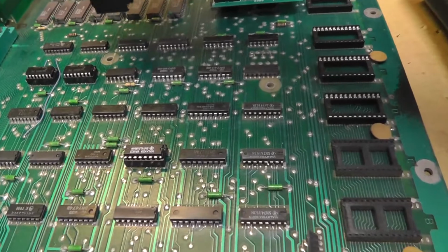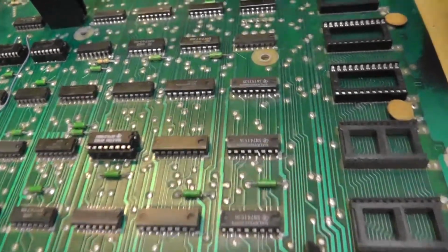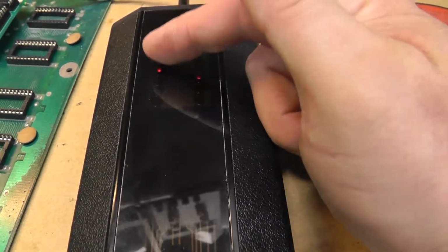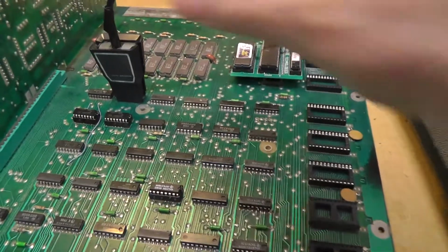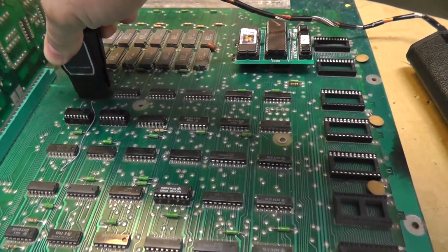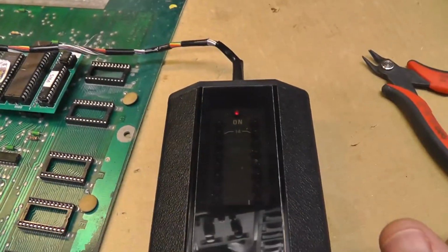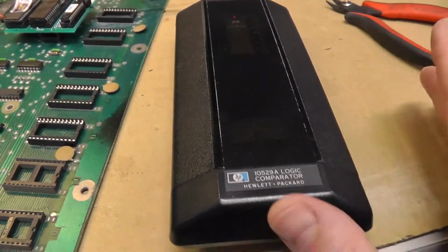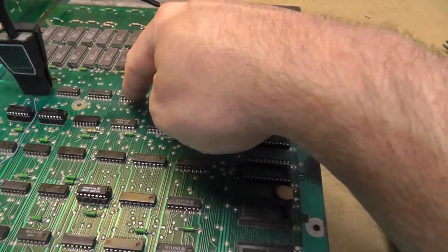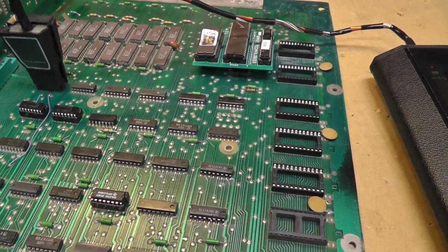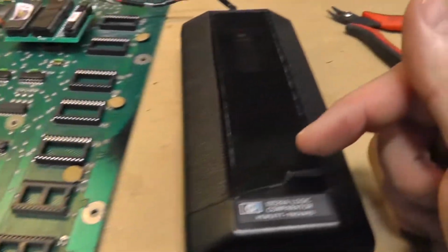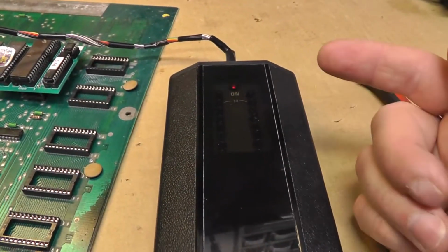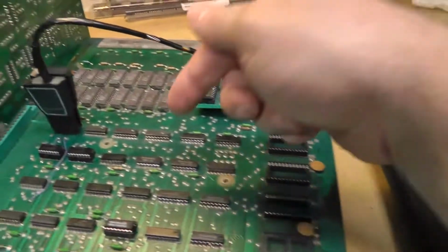Alright, and then let's check this one here. Now we got 4, 7, and 12 on that one. And if I go to the last one, it looks good. So either there's some timing issue or just some chip differences between the 9322s, I guess, and the 157 that I have in here. I don't know why those are reading differently than my chip. Doesn't necessarily mean they're bad.